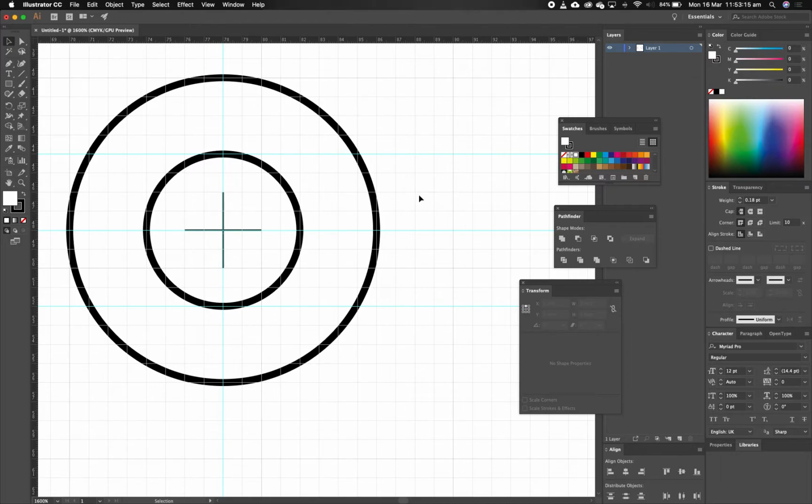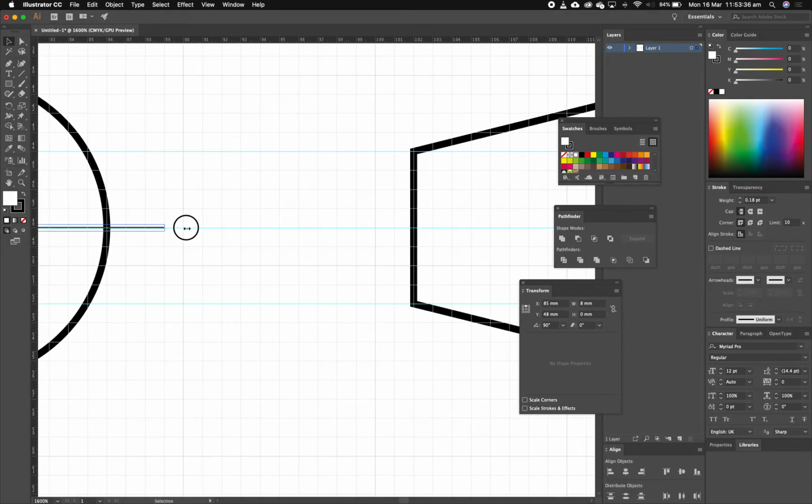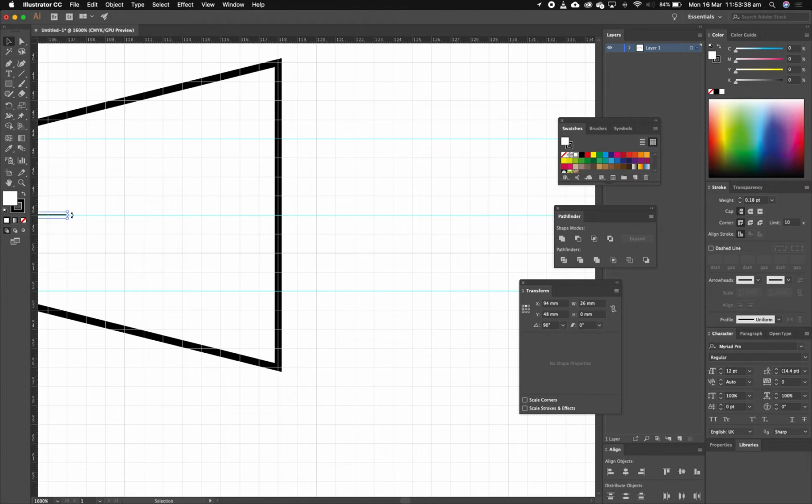Yeah, I can now select this line here. I move it across. Whoops. Press undo. I start moving across. I press shift option to drag it across, and I've just duplicated it. Okay. I can now resize this so it goes across the whole distance along here.